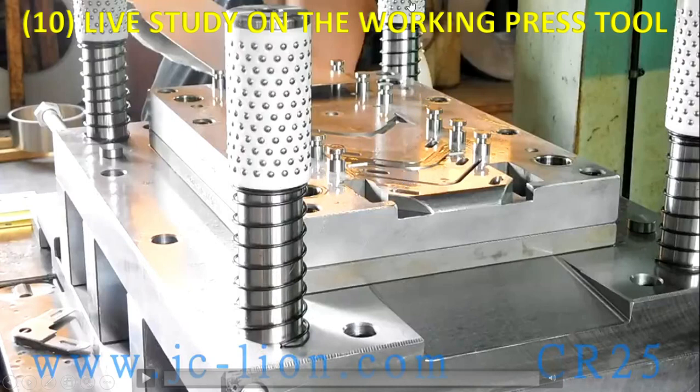And apart from this, we have a floating stripper on the moving half to hold the strip before the operations go on. And one more particular thing is, because of all the various complex operations going on, the alignment of the press tool is very important. So you see ball cages placed here in all the four pillars. These ball cages will maintain a perfect alignment between the two moving halves, the top half and the bottom. So you just watch the video now.